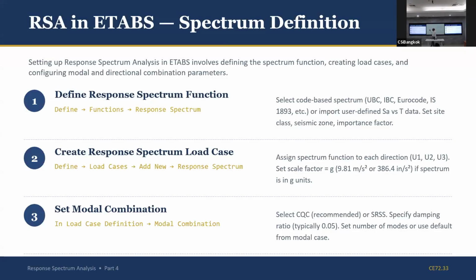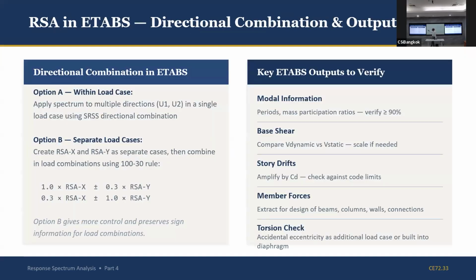So response spectrum in ETABS, spectrum definitions, functions, all of that is here. Then verification of the model information, base shear comparison, the load cases, directional combination, we talked about that. So all of that will now become important for you.